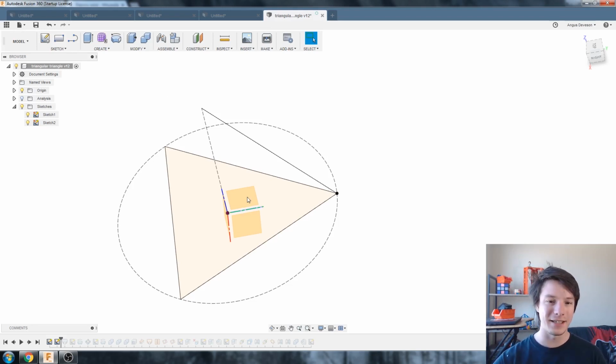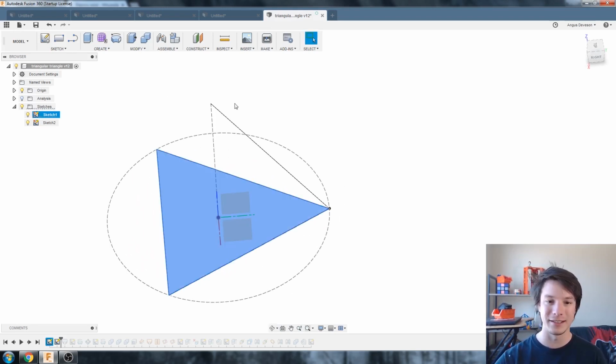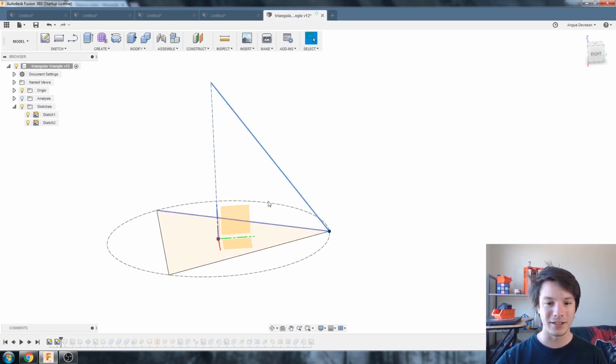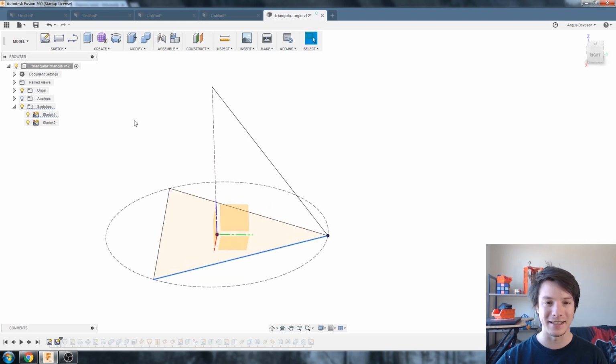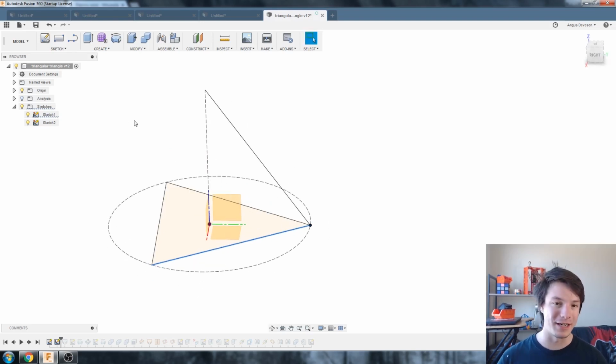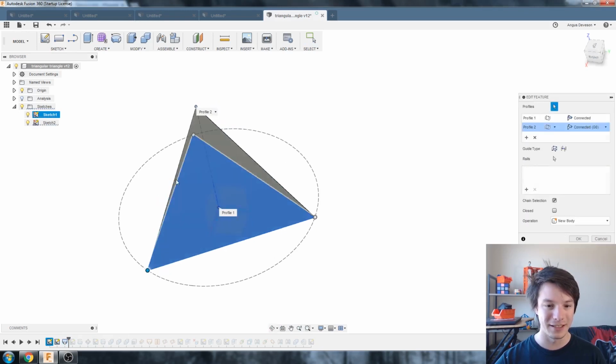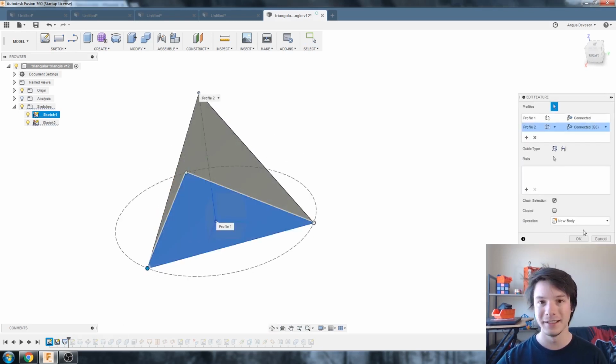So basically, as I showed in that previous video, I've got a sketch here and another sketch here. And those edge lengths are exactly the same. And that's what I'm using to create my regular tetrahedron scaffold. And just to show you again what the loft looks like, here is a lofted tetrahedron. So edit feature, it's the profile here and the point here. And that goes up to a point and leaves us with perfect regular edges.